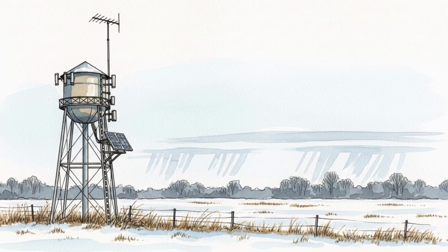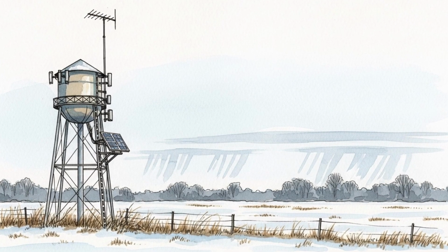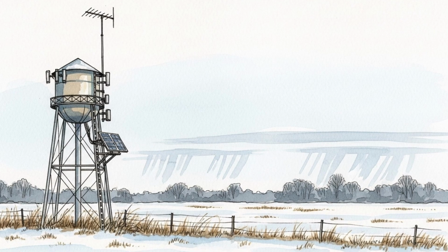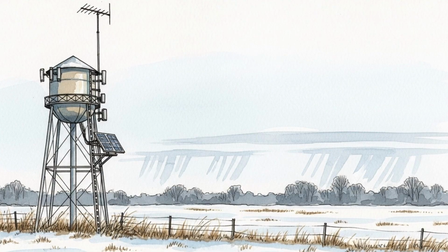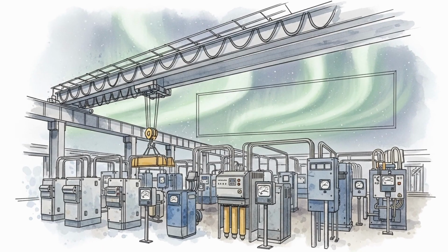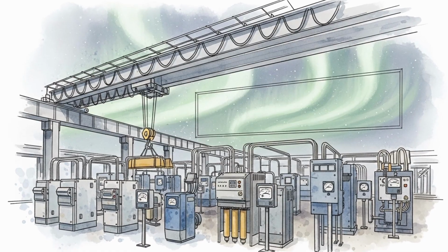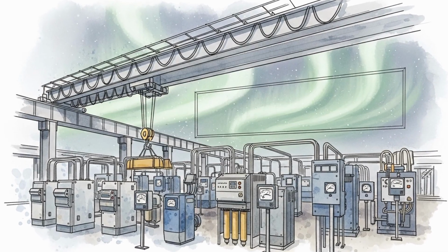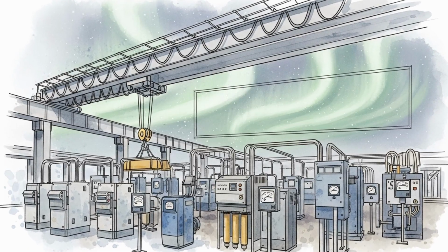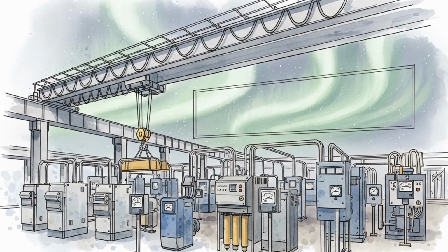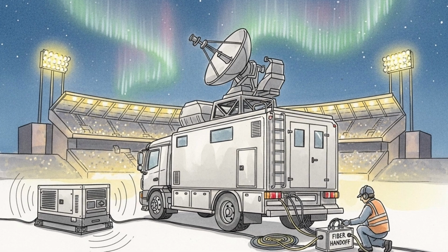Baseline severe scenario. A fast shock arrives. A sudden commencement is recorded on ground magnetometers. Within tens of minutes, upstream measurements at the L1 point confirm strong southward BZ. Kp rises to 7 or 8, and DST drops below -100 nanoteslas. Power system operators enter storm posture. Neutral currents and harmonics increase but remain within operating guides. Voltage is held using reactive reserves. Some long east-west or north-south corridors show higher bias, depending on regional field direction.